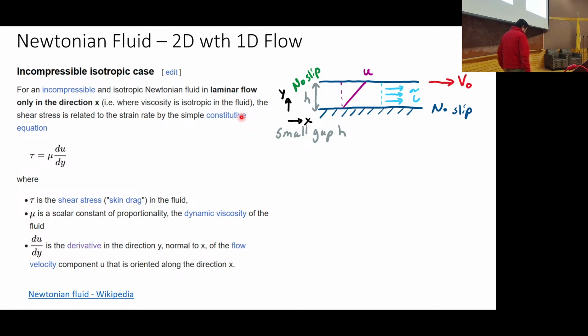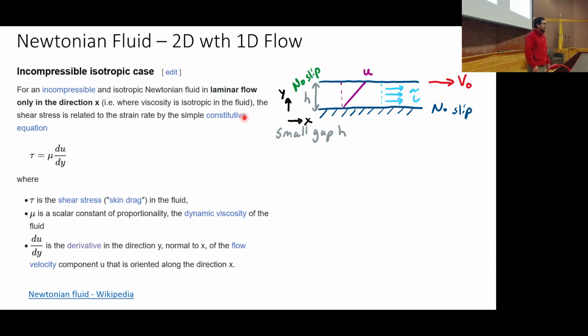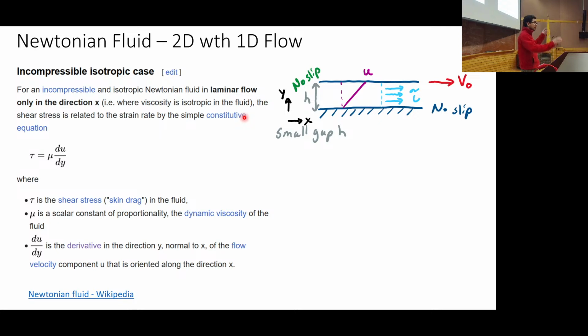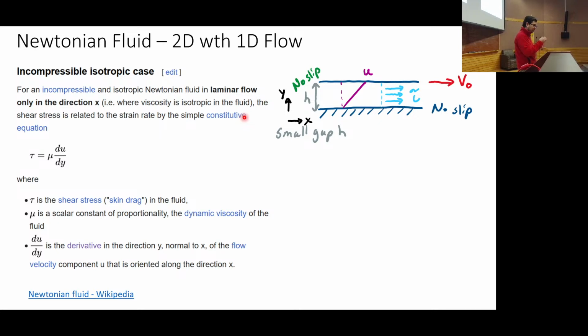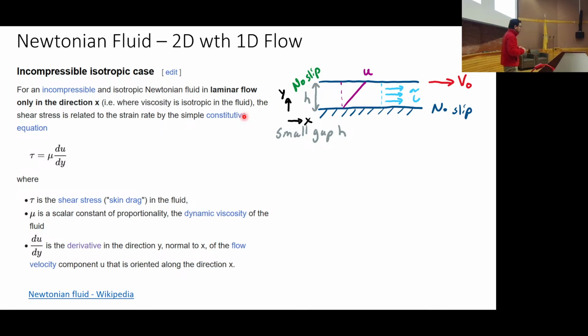So if the conveyor belt is moving, those particles, and I'm a solid, are going to move as the conveyor belt moves. If the walls are fixed, then yes, you're going to have a gradient there, and you're going to have essentially zero velocity right at the wall edge, and then it goes up, or the surrounding flow influences. So that's what no slip means.